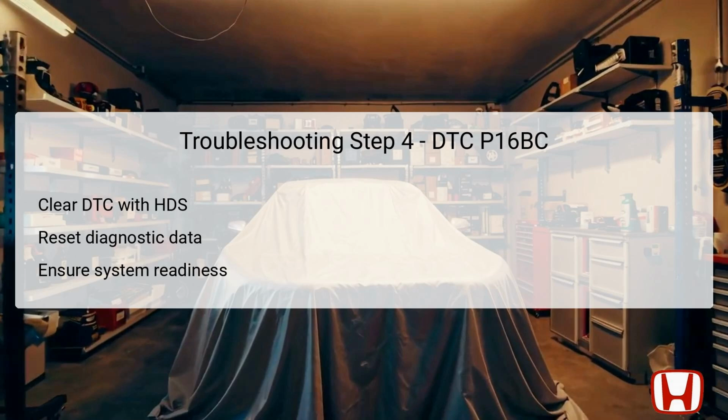Clearing the DTC will allow you to monitor the system's response to new conditions without interference from historical data. Ensure the HDS is connected properly and follow the prompted steps to clear the codes. After completing this step, prepare to start the engine and observe how the system responds.